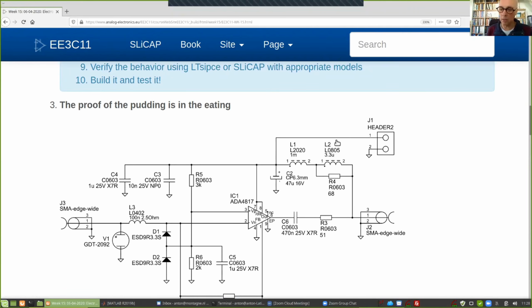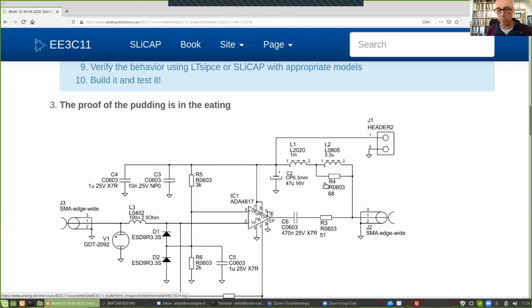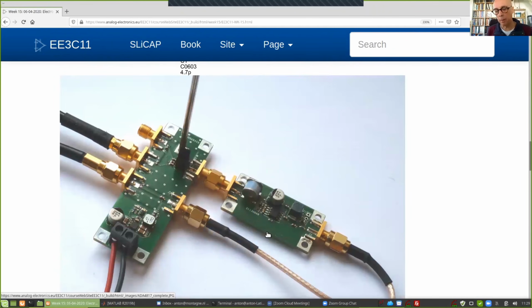On the other side is the same kind of circuit. But don't worry too much. You will use this with a separate power supply. Removing this all, just put your power here. Here you see the amplifier with the ESD protection. A very small device here, but another gas discharge tube here for sparks.